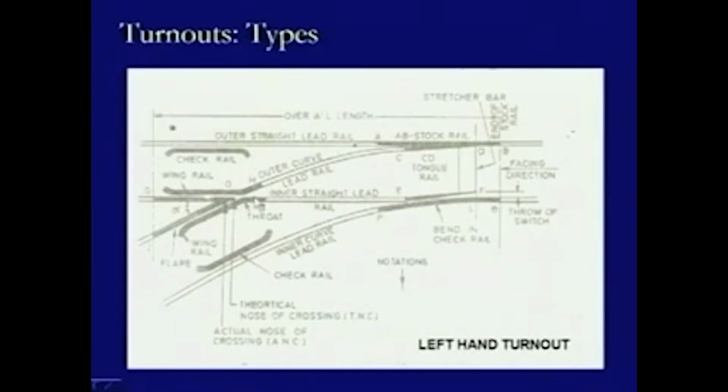Similarly, when we come back to this crossing side, what we find is that there is some distance left here, in this location between the two rail sections. Because of the bluntness of the connection of these two rail sections, some gap is maintained, and this gap is known as the throat of crossing. So, this is another terminology which we use, the throat of crossing.